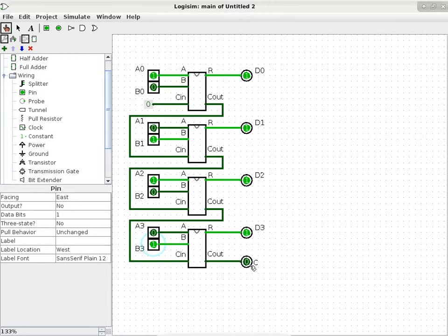How can you see the output of the entire thing? LEDs, right? Okay, you just use some low current LEDs, and you can actually see the entire thing. So you can flip the toggle switches, you can specify the input, and then you can look at the LED as the output. It's not a bad thing to do. I think it is really kind of a neat thing to do, just to see that, oh, I can actually do this on a circuit board using what we call jelly bean parts.